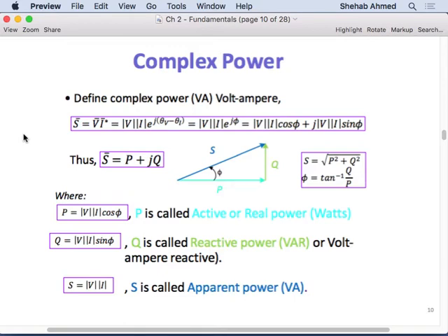As long as you understand the physical phenomena from the drawing, from the graphics, I think that's what matters, to me at least. So we divided up the instantaneous power into active and reactive power, and we called the total power that's being transferred from the generator apparent or complex power, and we discussed that last time. We discussed complex power in a single phase system.